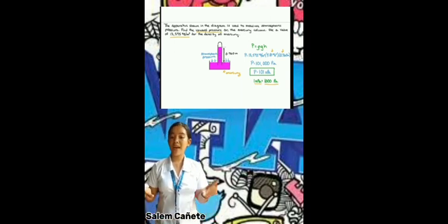Well, we know that the atmospheric pressure is equal to the pressure of the liquid column of mercury inside the test tube. And we know that the pressure of a fluid is equal to the density of the fluid times the acceleration due to gravity times the height of the fluid. So if we calculate the pressure of the liquid column of mercury based on the density of mercury, acceleration due to gravity, and height of the column, we will therefore know the atmospheric pressure.